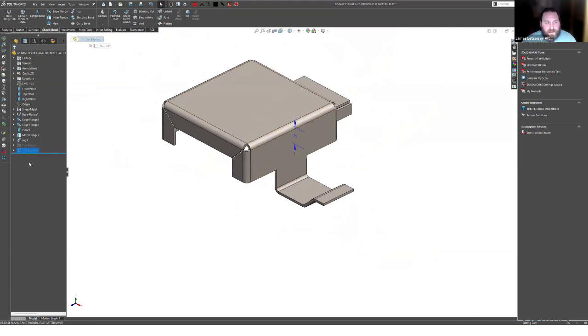And you can also see that we've broken our sheet metal sandwich rule. That cut feature is now outside of our pieces of bread. We don't want that tomato underneath the bread. We want it up here in the sandwich. So what we can do, there is another tool in the sheet metal suite that's right up here above the flatten tool, the unfold button.